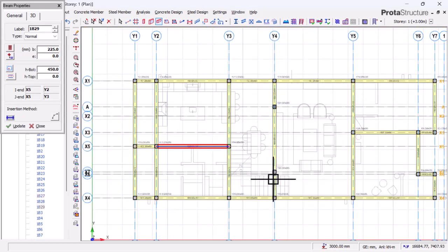This is what I'm talking about: this span is too wide for our slab here because of deflection. This is above 30 square meters. This is about 40.6, like we did from our GA. So we're going to cut a beam across this.